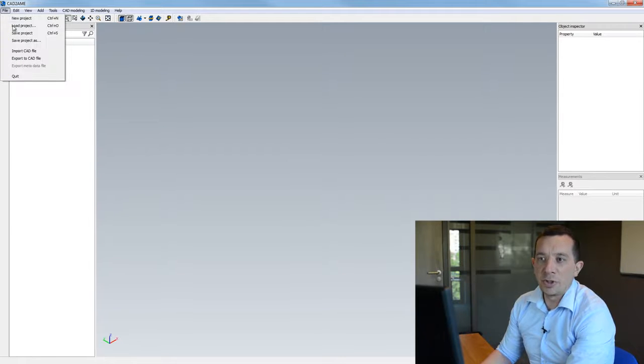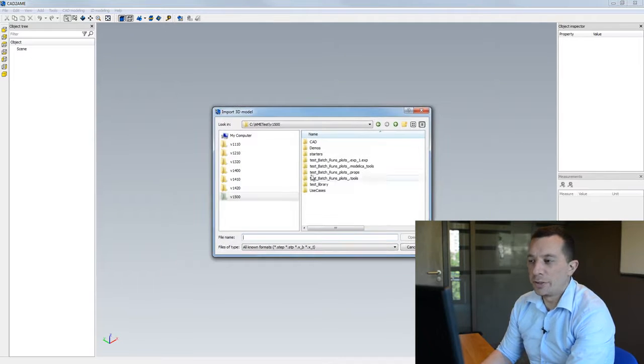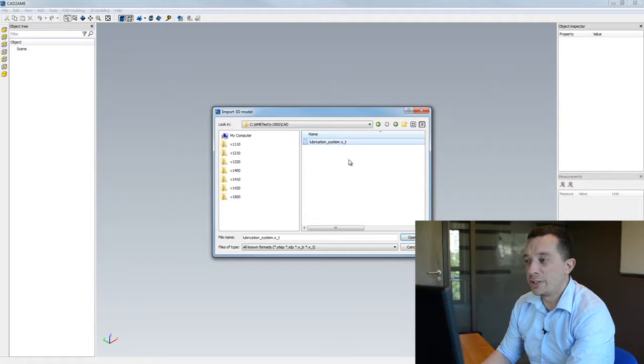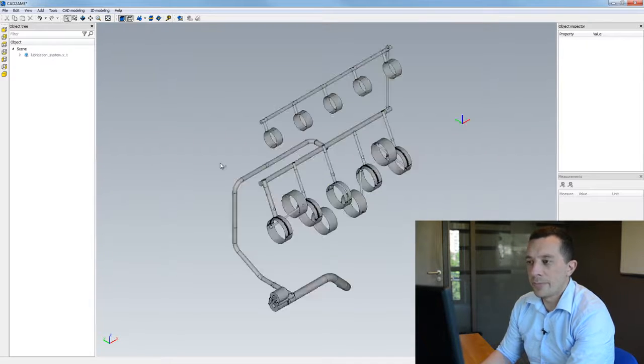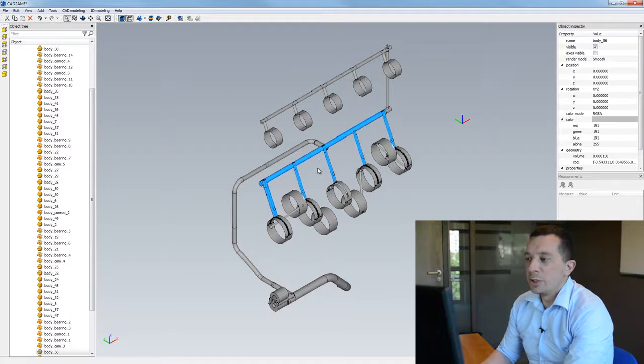And I'm going to import a CAD that is the fluid domain of the engine lubrication system. So the file is loaded, and before doing a primitive association to basic CAD bodies that will afterwards be your components in LMS Amesim, I'm going to process the CAD in order, for instance, to create and split these bodies into the main gallery and the different feeding drillings.